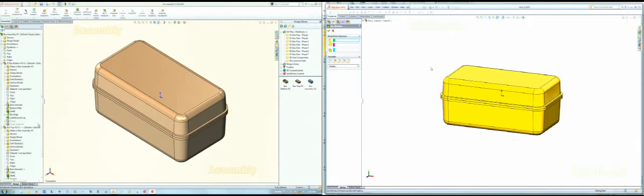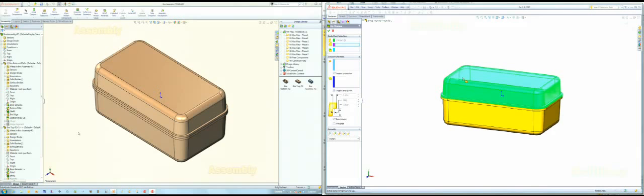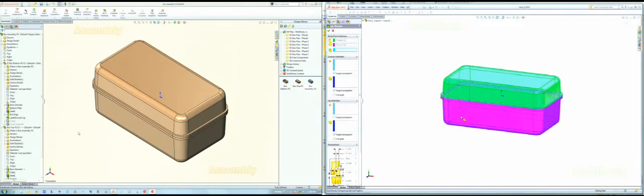What it wants to know is which two bodies you'd like to put the lip and the groove on. The top one is going to be the lip, and then it jumps down and says where do you want to put the groove, and we're going to put it there. Then it asks what's perpendicular to all that, so we'll know which direction to put it in, and I'm just going to pick the top plane again. Then it automatically jumps to the groove. I might have got those inverted a minute ago.